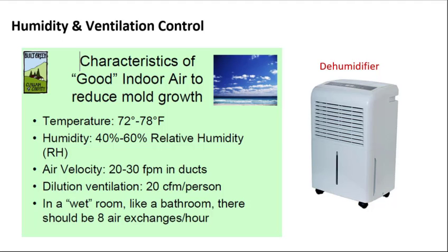Some specifics on conditions for reducing mold growth are provided here. For homes equipped with modern HVAC systems with temperature and humidity controls, proper functioning should be checked to verify values around those shown on the slide are maintained. A dehumidifier can also be purchased to maintain relative humidity levels in certain rooms of the home.